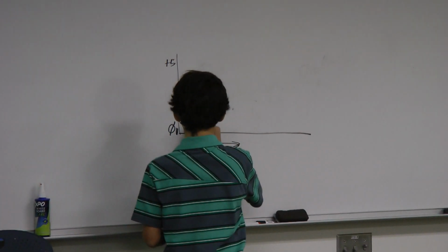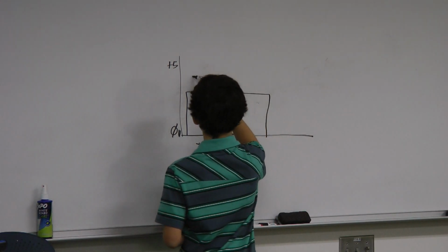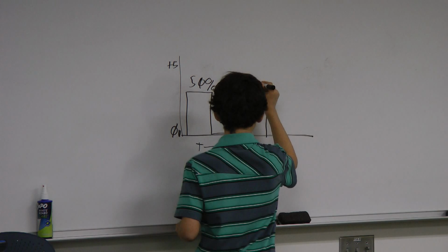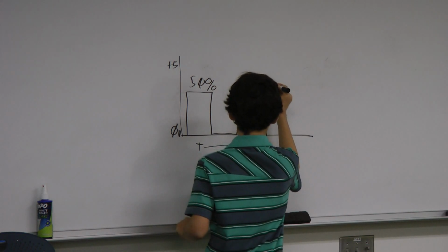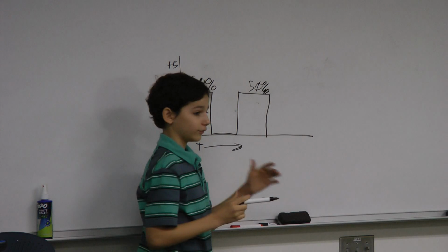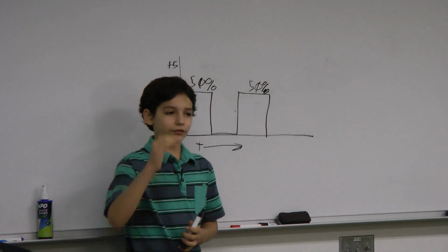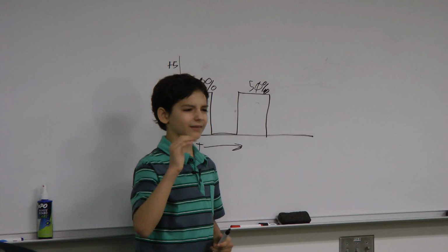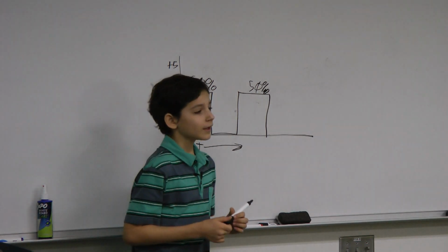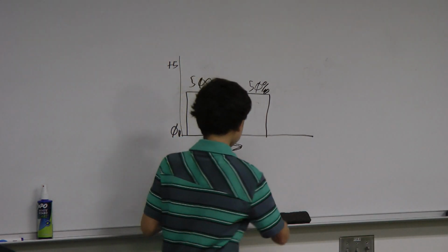What we can do is have it 50% on and 50% off, so it is on for half the time and off for half the time. With an LED, you can vary the voltage some, but it doesn't work well because of the way an LED works. What you do is vary the pulse width. So this will be at half brightness.